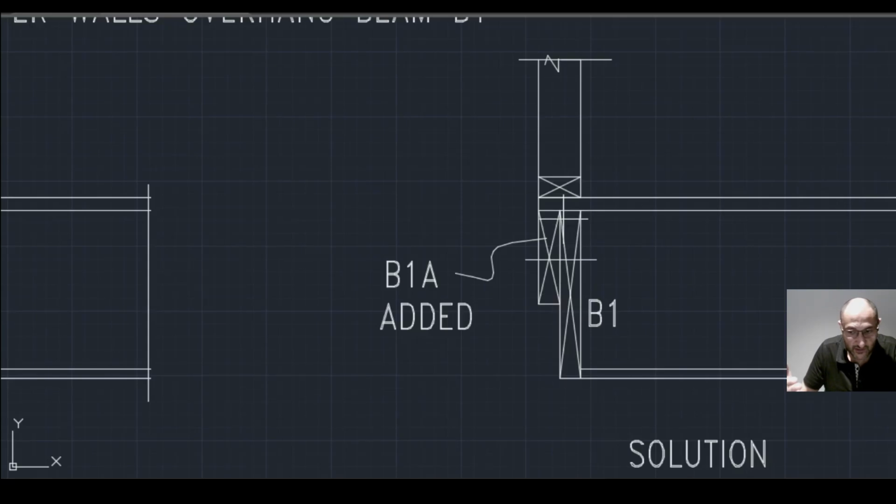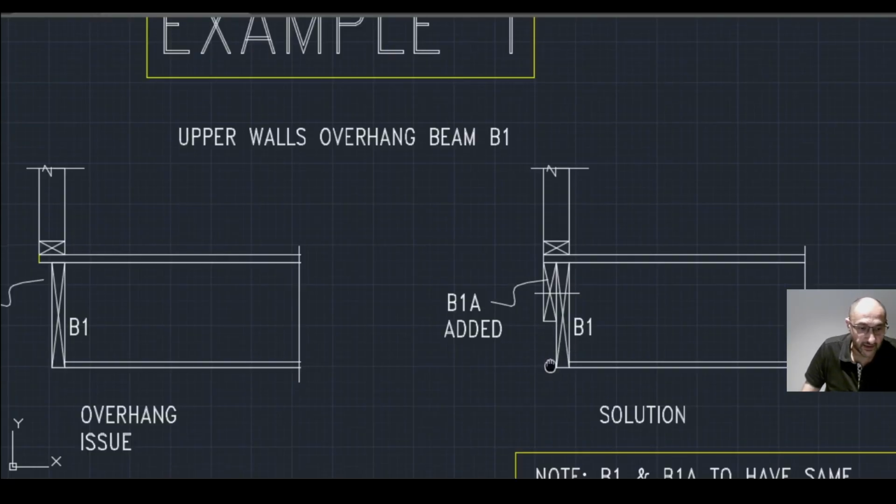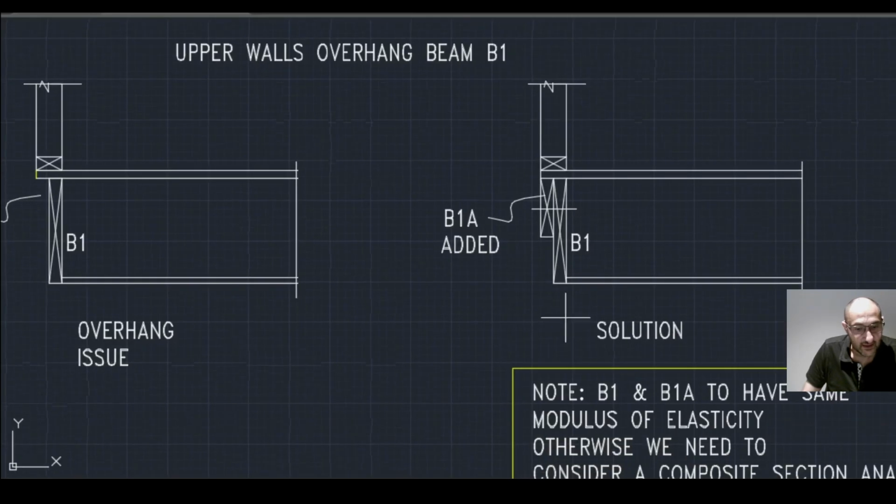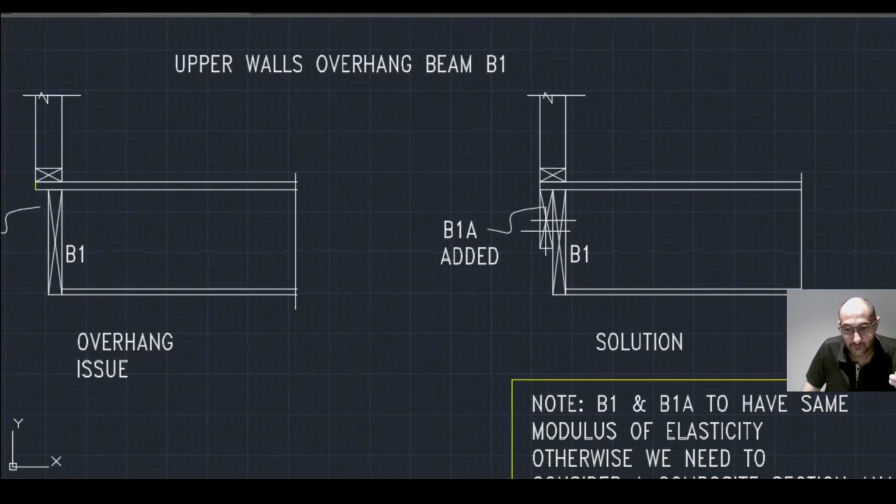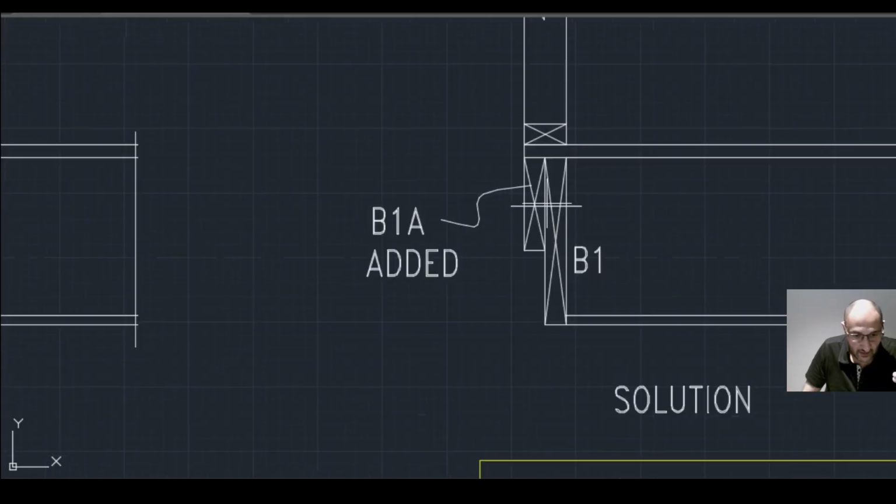Now once we determine the shear stress, tau, we can then work out how many fixings, could be screws or bolts, are required to keep both sections unified. We also note here that the fixings only have one shear plane, which means that the screws or bolts will only shear in one location.